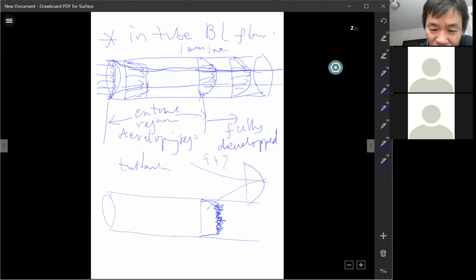It's turbulent. But if you take the time average, you will see a profile like this, the averaged velocity profile. If you average out those fluctuations over time, then it becomes just a straight line. See, it fluctuates about a mean value. If you average it for a long period of time for this velocity profile, it will become like this. Don't worry about the fluctuation. In engineering applications, we only care about the mean flow, mean velocity, mean speed, whatever. We don't care about the fluctuation from time to time. If you average out, it's just like this.